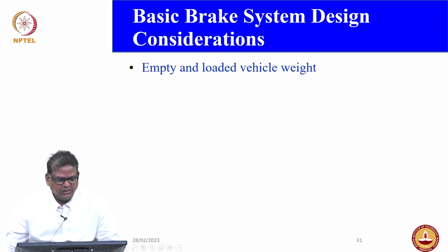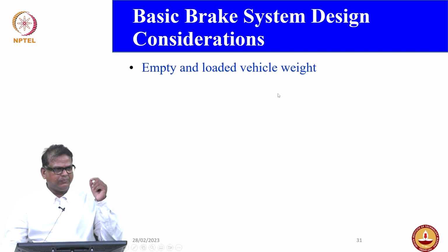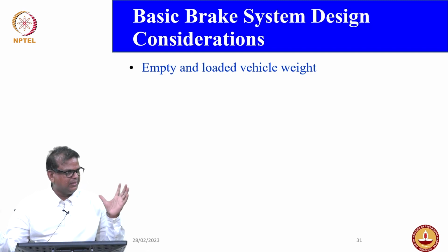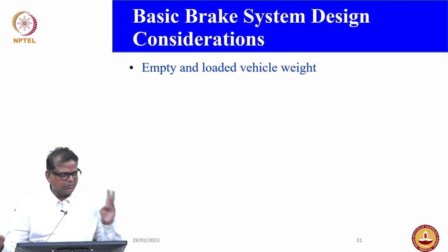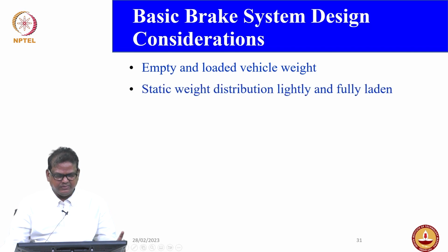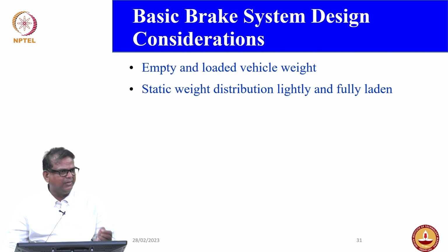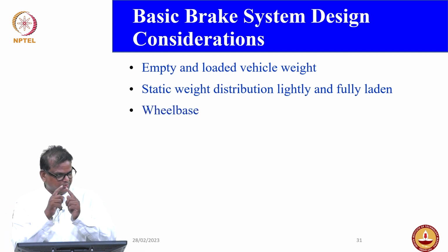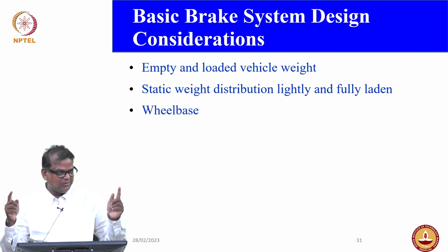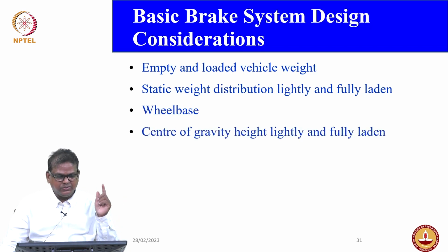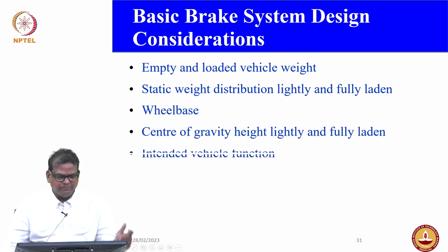Now we will go to an important thing before going into the design considerations. You have to think about the loading aspect, when the vehicle is empty or fully loaded. Both conditions we need to think about for designing the brake system. Also, the static weight distribution for lightly and fully laden. Laden means loaded.